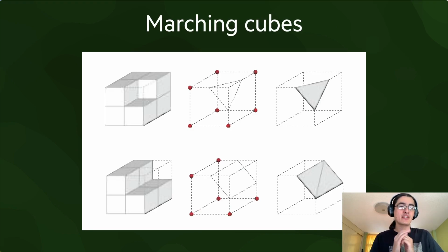Then another interesting part was when you go from the voxelized model to the mesh that you want to get for something like a 3D city model. Here you do not just use the surfaces of the voxels as we did, because this will lead you to a blocky model. As you have seen, even when you go to very small voxels, it will never look quite right. So there are many algorithms that you can use to get a better result.